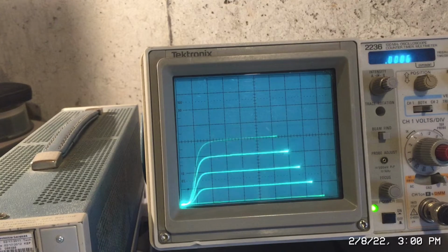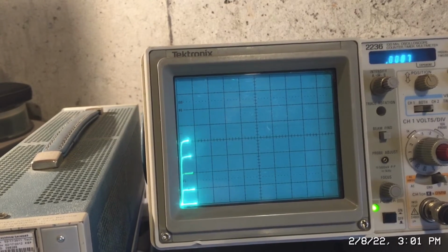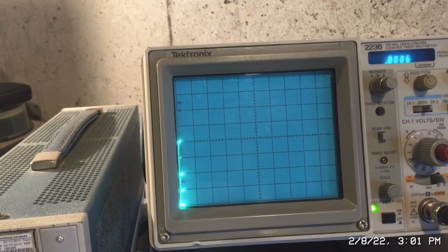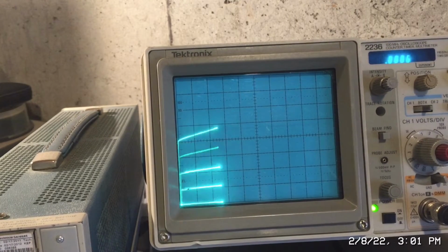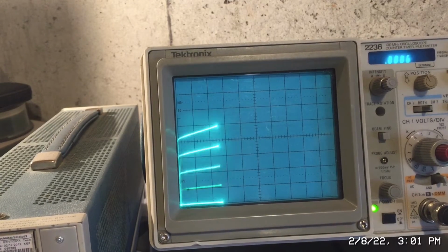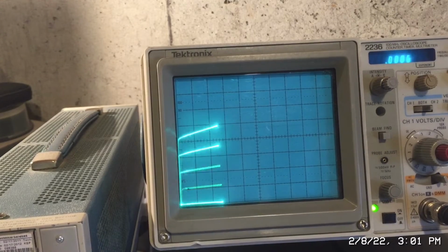I'm back to my baseline transistor again. Another measurement that you could make very easily is the breakdown, secondary breakdown voltage. Okay, and what we do there is, now remember this axis is my collector emitter voltage, right? And if we check the spec, which I'll go back to in a minute, we see that the breakdown voltage is rated at 40 volts. So now I'm at 10 volts per division. Let me change that to 5. It might be a little easier to see it with a little more resolution.